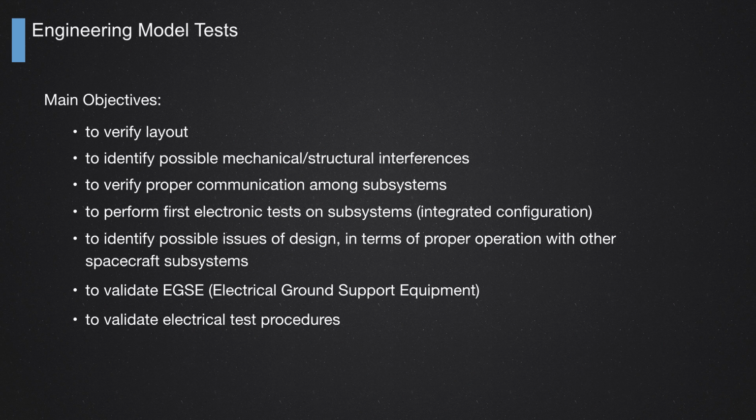Then when the spacecraft is completely finished and integrated, we do a full test of the complete integrated spacecraft once more. We do all the tests again: vibration test, thermal vacuum test, EMI/EMC testing, mass properties, as a fully integrated assembled spacecraft, to make sure it's ready for flight. Why? Because we also want to make sure that the handling and manufacturing of the spacecraft was done properly according to the specification. Let's talk now about the tests to be performed on the distinct models of the spacecraft.